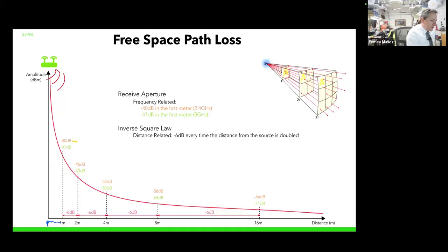Double the distance, from 1 meter to 2 meters. It says here that we lose 6 dB. Double the distance, 1/4 of the power. So how come 1/4 of the power is minus 6 dB? Not minus 6 dBm or minus 6 dBi. No, you just lose 6 dB, 6 decibels.